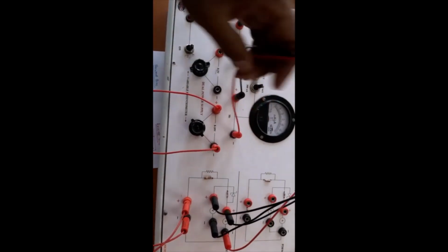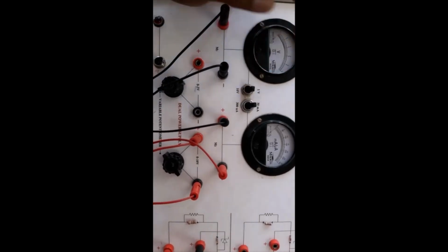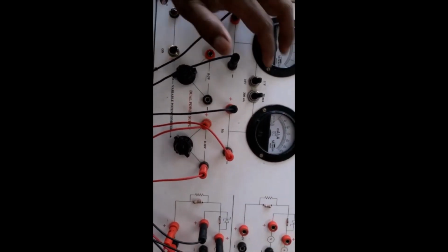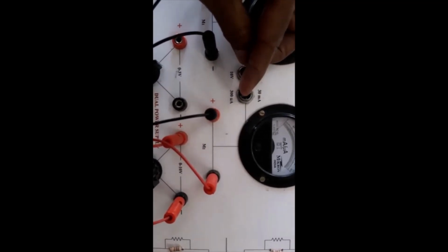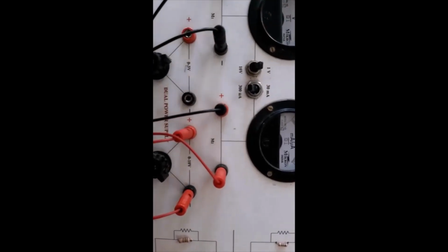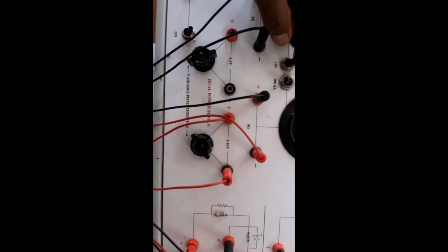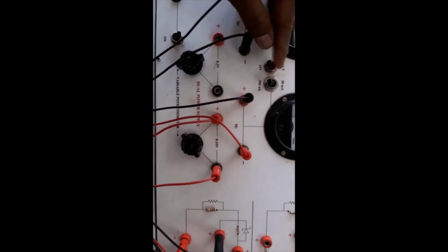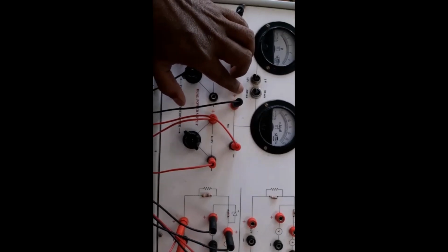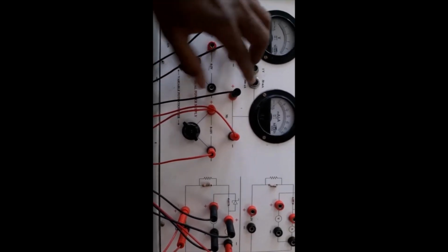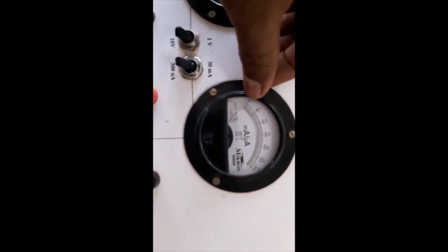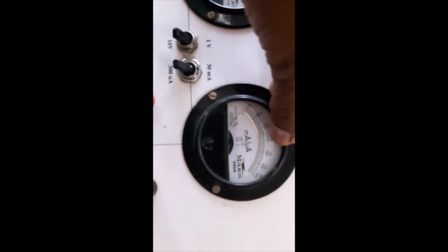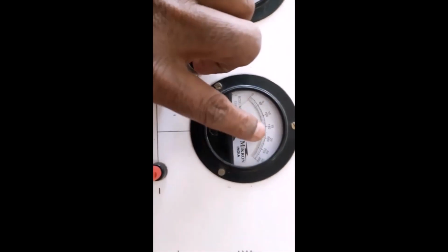Now we have to change the meter ranges. As it is reverse bias, the current is small and it is in microamperes. Switch this to the 0 to 300 microamperes range. Similarly, as you are applying a higher voltage up to 10 volts, you have to change this to 10 volts. And remember that as you are in 0 to 300 microamperes for the ammeter, you have to use the bottom scale or the second scale, because the second scale is from 0, 50, 100, 150, 200, 250 and 300. So you should take the readings from the lower scale only.